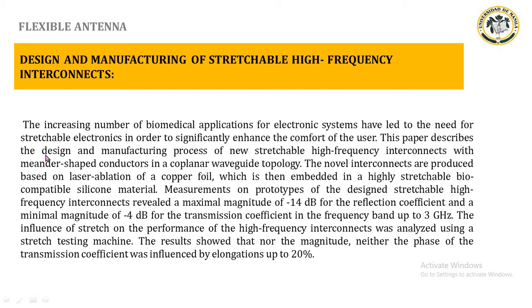This paper describes the design and manufacturing process of new stretchable high-frequency interconnects with meander-shaped conductors in a coplanar waveguide topology. The novel interconnects are produced based on laser ablation of a copper foil, which is then embedded in a highly stretchable, biocompatible silicone material.